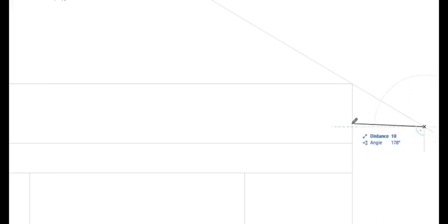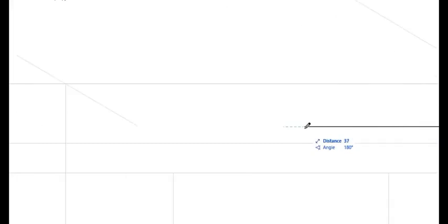So I'm just going to draw another line here, but with the faint pencil up to this point here. That means that is where my eave projection is going to be, and this is where I'm going to have my fascia board. So from this point here, I'm going to draw a line. Assuming I have a fascia board of 200 millimeters, so measuring 4 millimeters, that is to the scale. Draw that there like that.